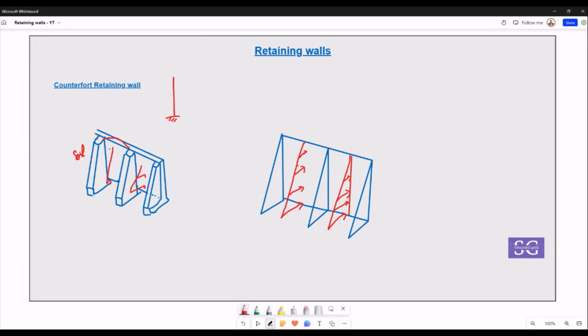The way to treat it is to provide counterforts. Essentially, the earth pressure is pushed on these wall panels, and those wall panels transfer the forces through reinforcement or any other mechanism, whatever the type is, to the counterforts. The counterforts take this as an in-plane load, as a push-pull action. If you push this counterfort in this direction, there will be a pull in this case and a push in this case.